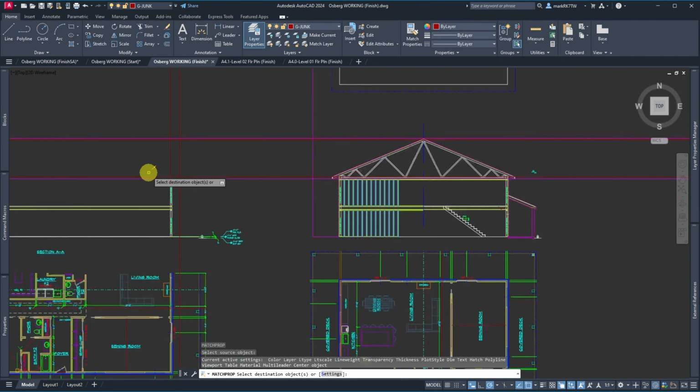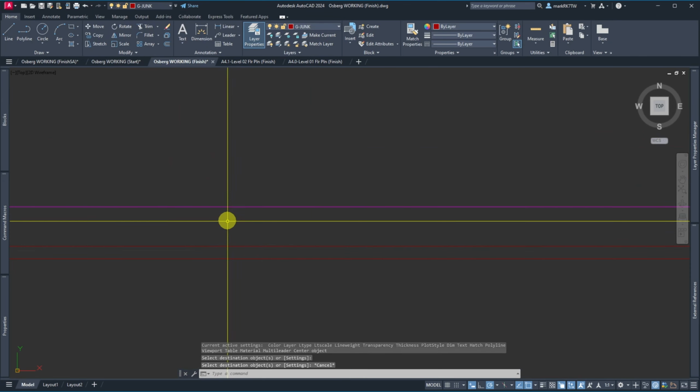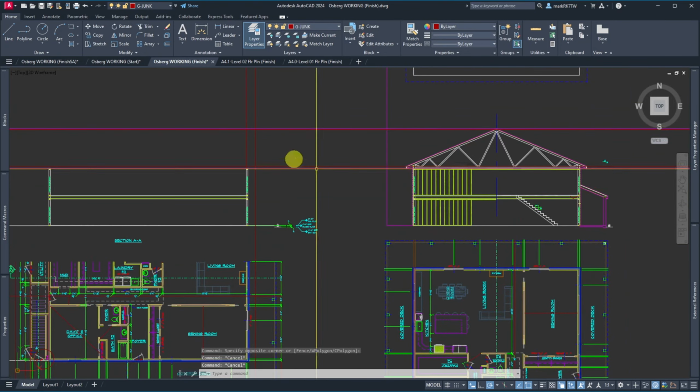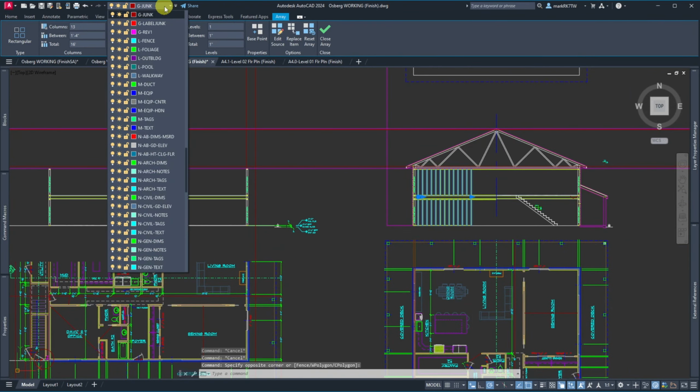And we will want that up here in this thin line here. Oh, it didn't do it. You know what that just told me? This array, look at it, it's on the junk layer. If I went to print this section, my junk layers don't print. So when I created this array, I was on this layer. And that will cause you headaches.